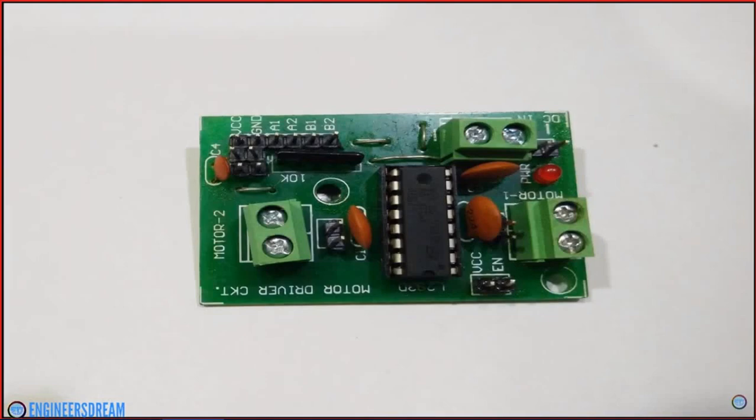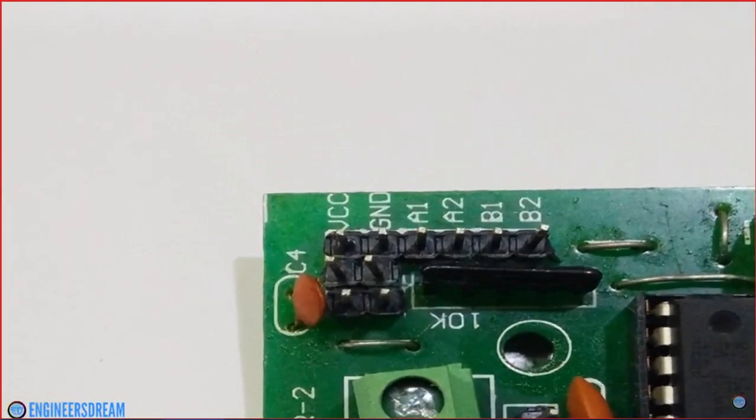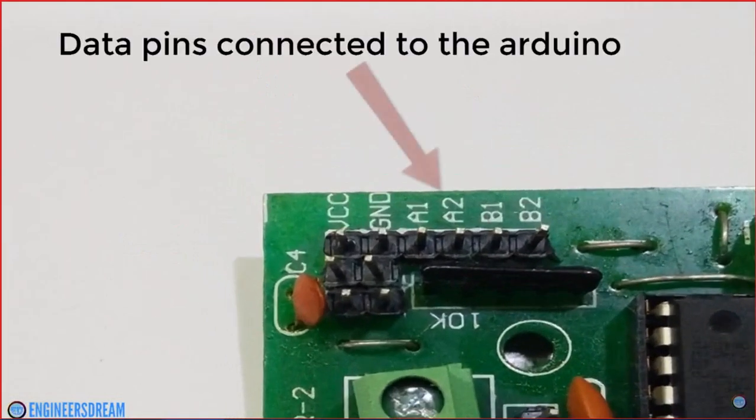Now if you look at the first motor driver, it consists of 3 green sockets, 2 at the bottom and 1 at the top. It also consists of 4 data pins on the top left side. The input pins of the L293D motor driver IC, that is pin number 2, 7, 10 and 15, can be accessed from the top left side over here at A1, A2, B1 and B2. To these pins, we will provide inputs from the Arduino's data pins.